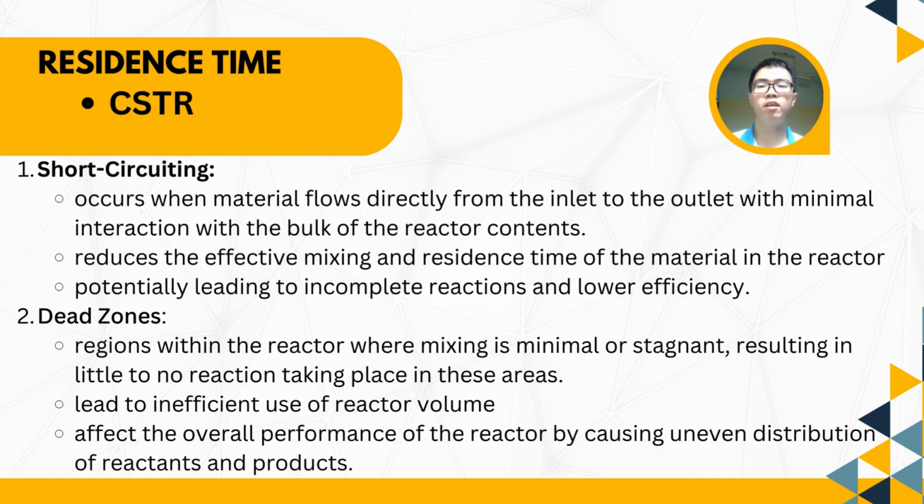For bypassing, it can reduce the effective mixing and residence time and lead to incomplete reaction and low efficiency. While dead zones lead to inefficient use of reactor volume and affect the overall performance of the reactor by causing uneven distribution of reactants and products.